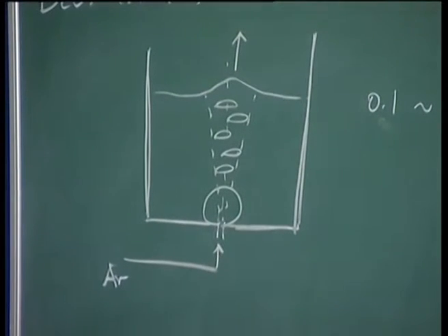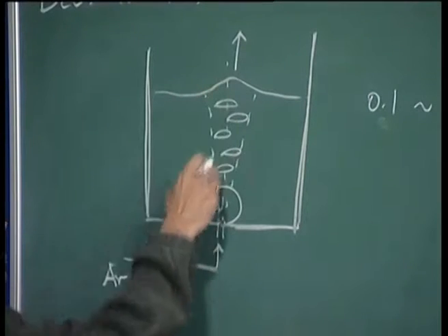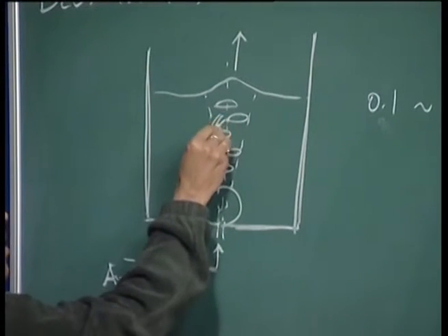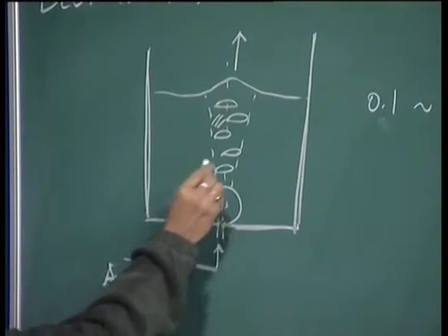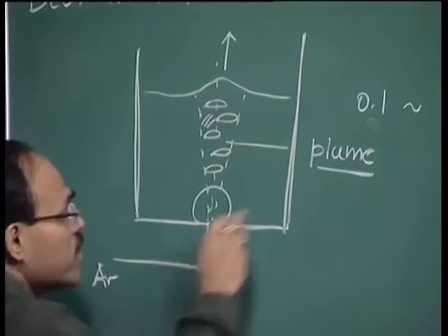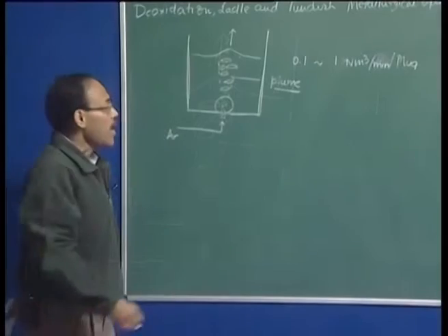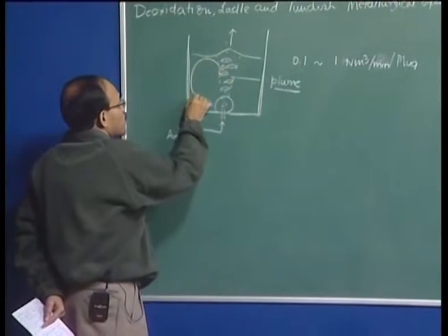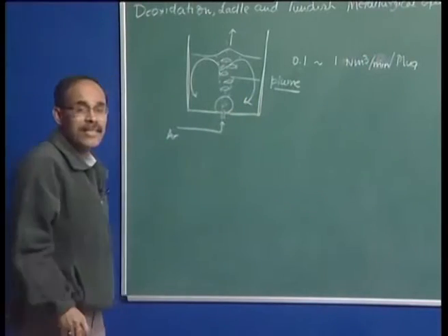So, the two-phase mixture that we see at the center, with some liquid steel and dispersed bubbles, is typically called a plume. The injected gas, given its buoyancy, rises to the free surface, and as a result it induces a turbulent recirculatory motion of liquid steel in the system.